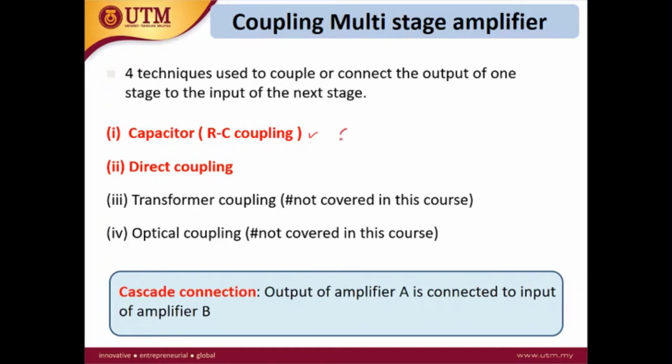The capacitor coupling will block the DC, and at the same time it will allow the AC signal. This is an important concept that you need to understand. Please refer to the third example in the previous chapter, where I showed you the difference in the output waveform before and after the capacitor coupling.